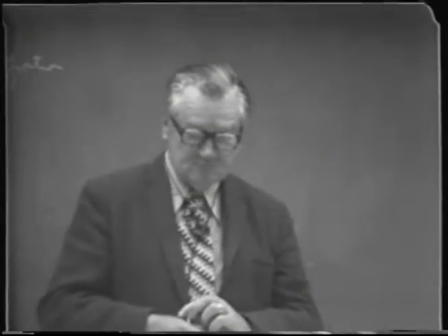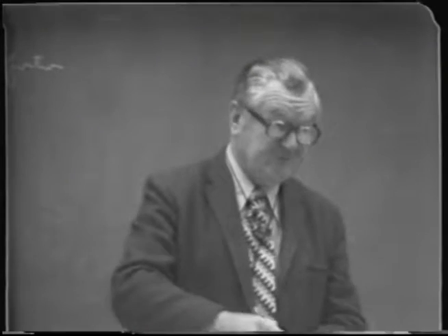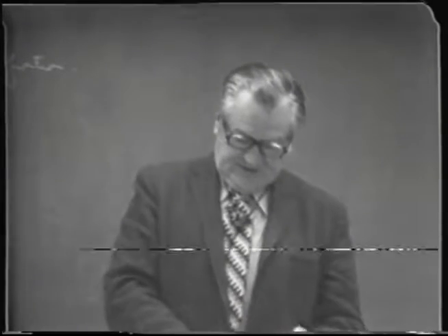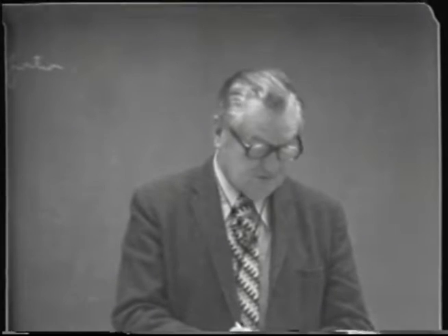Well, I'll have more to say about that in a moment, but turn to the second page of that handout. It is a plot of the equilibrium curve, or the XY relationship, where we plotted the mole percent isobutyl alcohol in the liquid phase on the horizontal scale and in the vapor phase on the vertical scale. So here you can see again that at very low percentages of isobutyl alcohol in water, you have a very great enhancement of the volatility. Much more volatile than water.